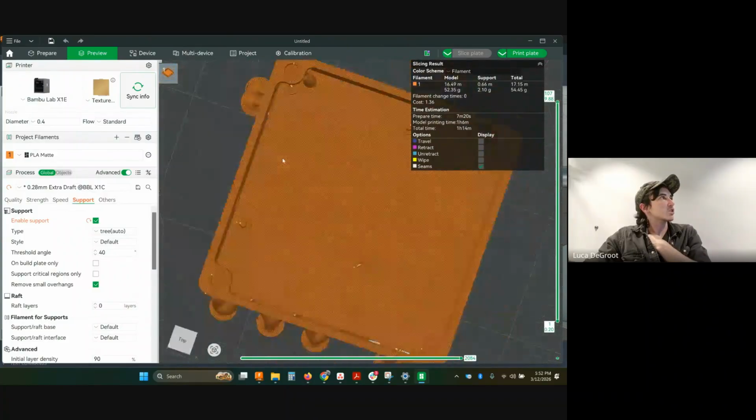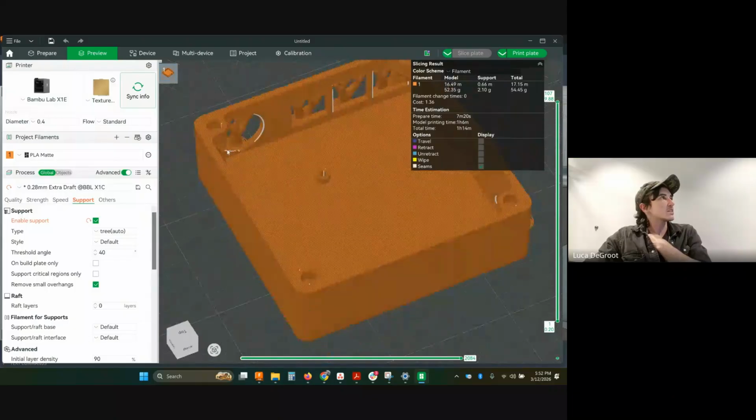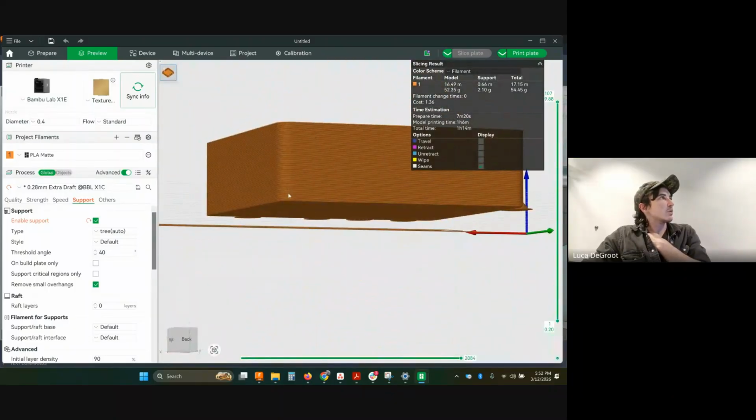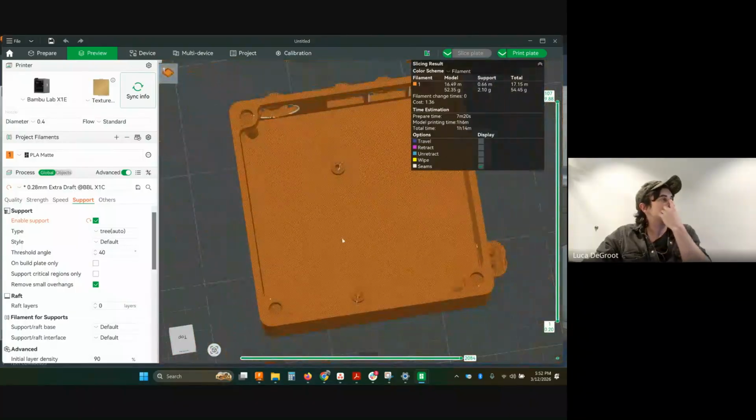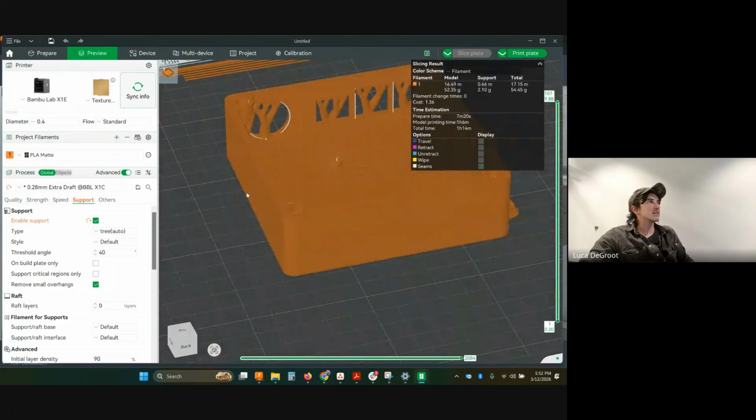Yeah, so there's some internal trees as well as some external trees. We might consider putting a chamfer on the bottom if we wanted to. That actually can be really helpful for removal of 3D prints, or also preventing this wall. You'll get what's called an elephant's foot on that first layer, because it goes a little slower in order to make sure there's adhesion. So it kind of bows out just slightly in here, right on those first few layers.